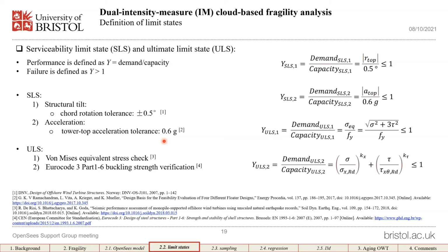Is it linear, or do you use a nonlinear one? You are using fiber sections, so you must be using aggregators for the shear and torsion. Yeah, we were using a nonlinear steel material, the Steel02 model.